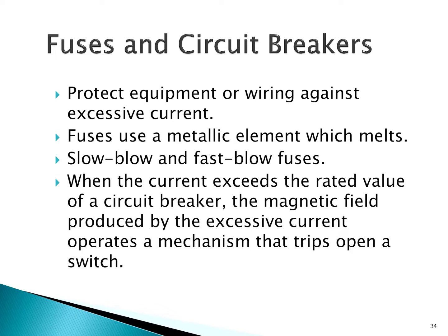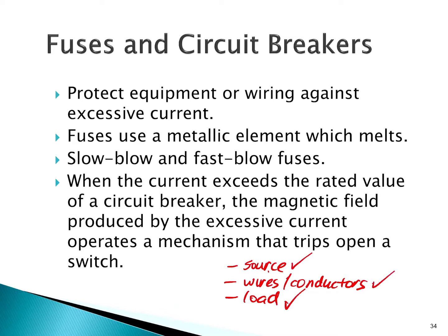So all of the components that make up an electric circuit are the source, the wires or the conductors, and the load. So we want to have overload protection to protect the source from overload conditions, the wires from overload conditions, and the load from overload conditions.